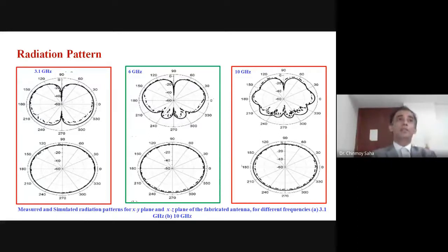So that's a very useful experience, because these are very small antennas, and measuring the pattern with highest accuracy is very important, because people are using the simulator to show the pattern. But if you really enter inside a chamber, and then you have the standard gain horn, and then you have to do the 2 antenna measurement technique or 3 antenna measurement technique or gain transfer method.